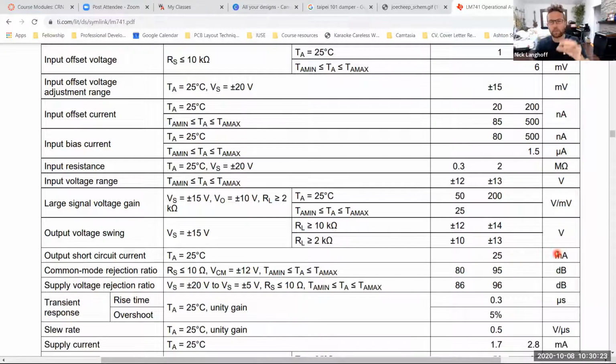It's a little 8-pin package. It is made on a silicon die. Currents at levels greater than that start to heat up the internal components to a point where there's enough thermal energy that parts start to fail. Components start to fail. So the answer to your question is yes, it can stress the power supply.